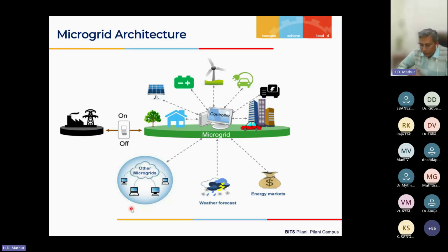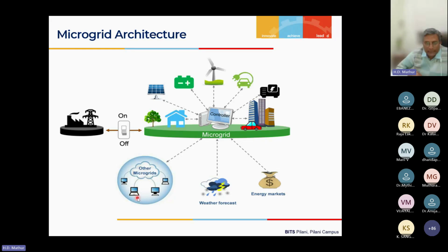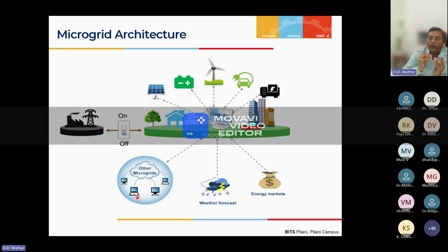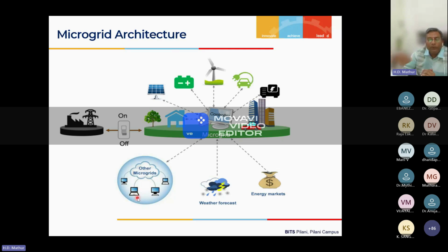But in general, those who are new to this domain and attending this talk should understand that suppose you have a certain load that has to be met with 5 different generations. If I have good forecasting techniques, I don't have to worry about thermal or hydro, because I know they are controllable sources. If I know they are to produce X, they can. But in order to make the system greener, I have added solar and wind. If somehow I get a good forecast, at least an hour before, or better, a day ahead, with almost no error, I would be very happy.